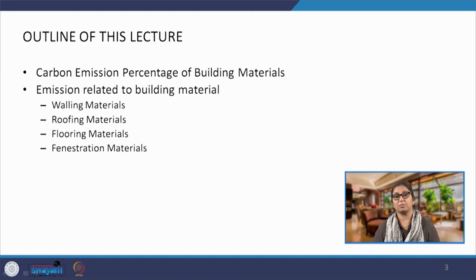So, for example, if we are talking about the brick industry, the fired clay brick industry, all the emissions from combustion of fuel on the site are scope 1 for this brick manufacturer. But when we use this material, brick, in our buildings, then it becomes scope 3 upstream for us, because it is something that has already happened. It is already embodied. The energy that has been expended, we call it embodied energy. So, it is not the amount of energy that is actually contained in the material, but the energy that has been consumed to produce this material.